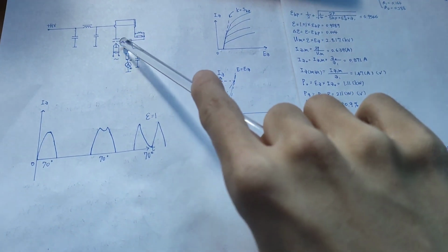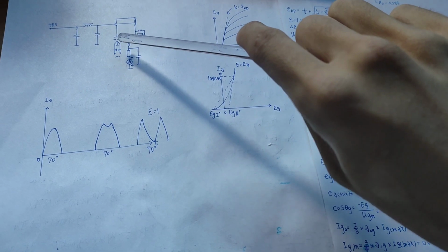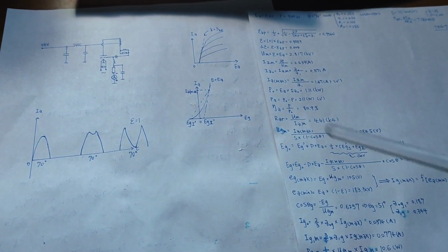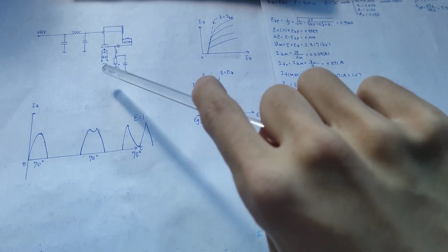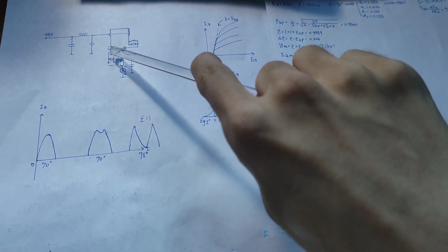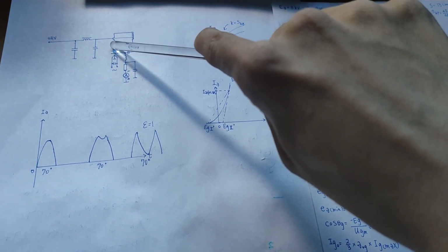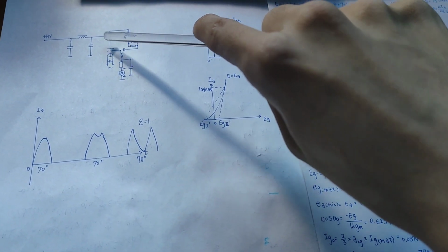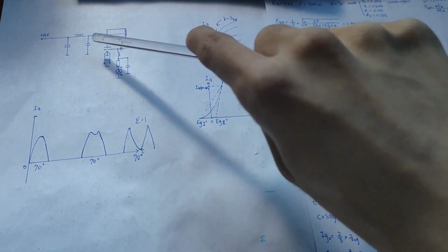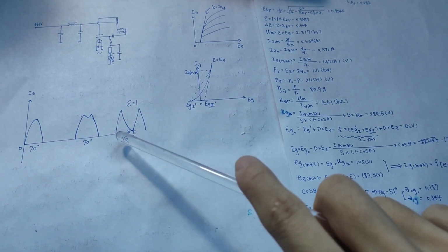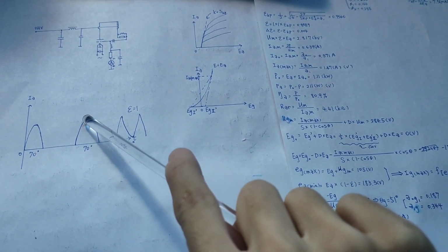So if the grid is more positive than the anode, which I mean is in a positive mode, because during the calculation sometimes you will find that the anode current is actually larger than the peak current the cathode can supply, or in the situation that the grid potential is much higher than the anode potential, then the anode will just be blocked, right? So all the electrons from the cathode will move to the grid to form the grid current. That is what you will see in these two waveforms. Why does the anode current have a small part missing?